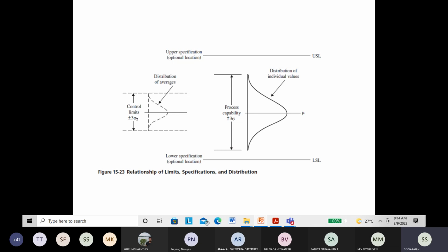And in machine drawing, you studied something called tolerance. I don't know whether you remember machine drawing. Whenever there is a drawing, you will have bilateral tolerance, unilateral tolerance, all these things. What is the tolerance? For example, if you take a shaft diameter, it has to be 25 plus or minus 0.01 mm. That plus or minus is a bilateral tolerance. If it is unilateral tolerance, you will have only one side.